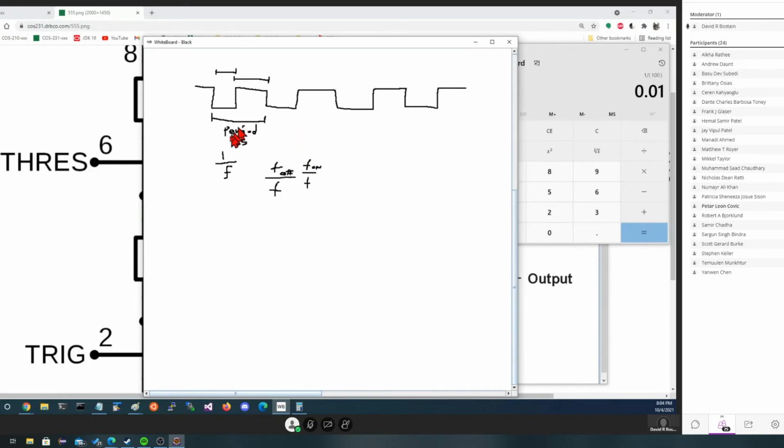We call the relative time the duty cycle. That's the on time to the off time. So if we're on for 60% and off for 40%, the duty cycle of that is 60% because we're on 60%. It's always relative to the on time. The off time, add them up, we get our 100, whatever units it's going to be relative to. We're going to be concerned about setting the amount of on time and setting the amount of off time to equal the period so we can invert it to get the frequency we might want to use.